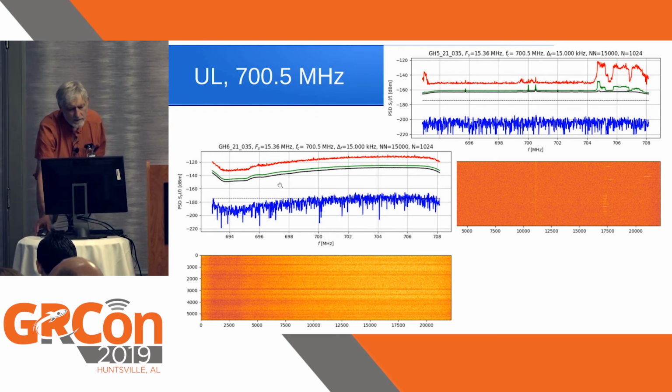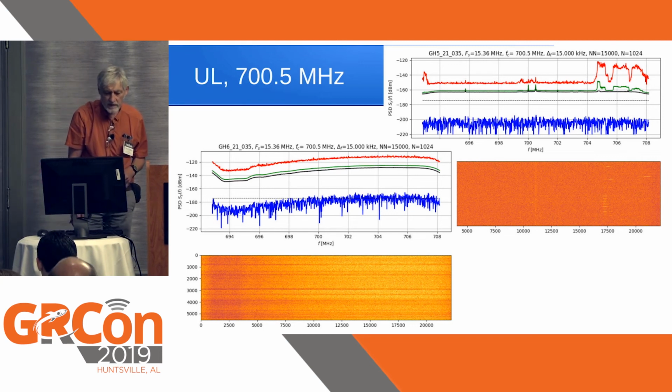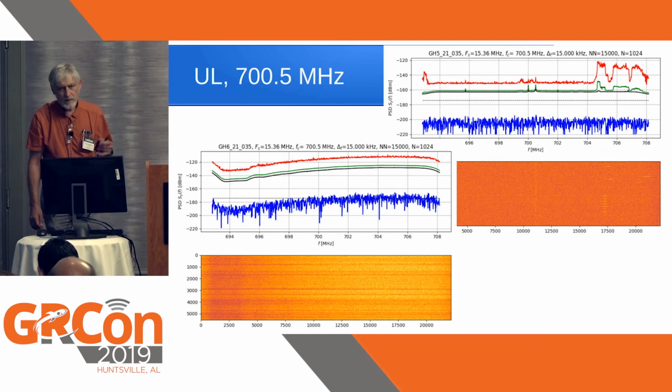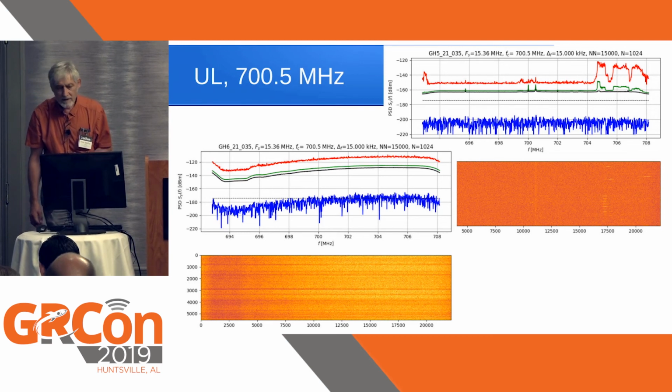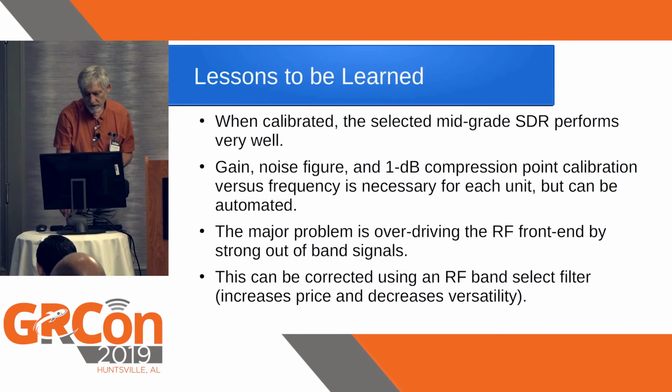And so basically that means on the left side here, that spectrum is useless. That plot is useless because whatever signals might have been there is actually wiped out because of that signal that you have in a different band that is strong enough and overdrives the input amplifier, the RF input amplifier.